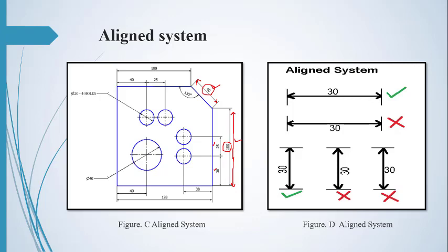dimension lines. Here you can see that in the line system I have explained that the unit should be on the dimension line and must be in the center. So this one is accurate. On the other hand, if you see the same unit is written in the center, but beneath the line, this case is improper.